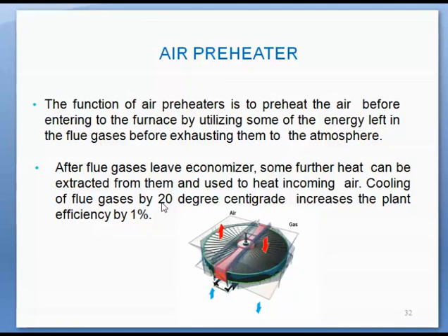Cooling of flue gases by 20 degrees centigrade increases the plant efficiency by 1%. So it is a very important factor that has to be remembered. Okay, this shows how important the air preheater is and how it affects the efficiency of a thermal power plant.